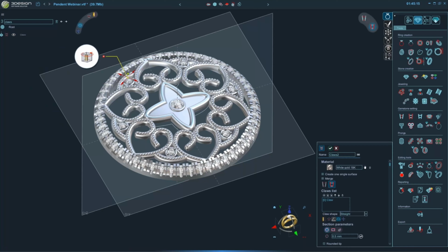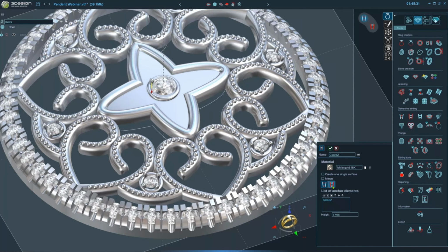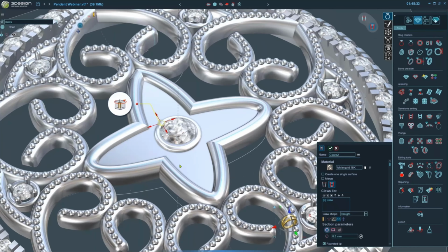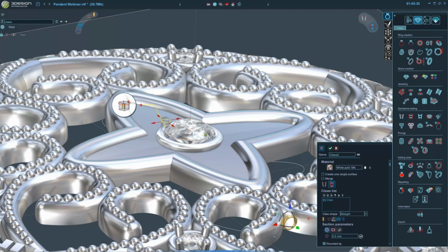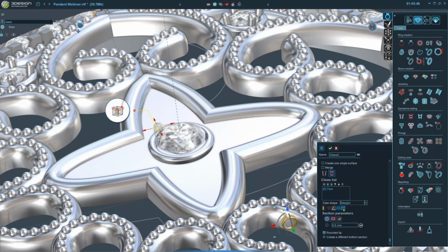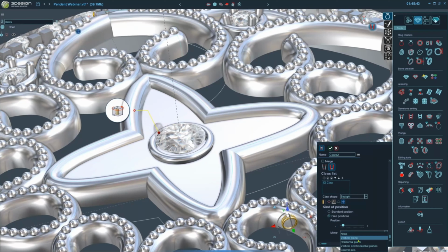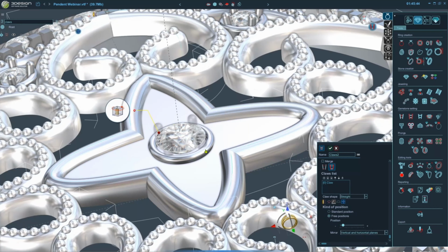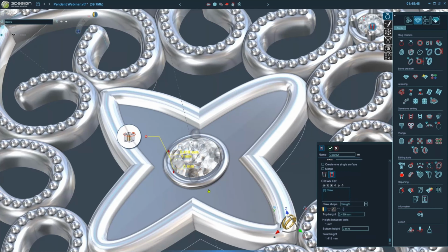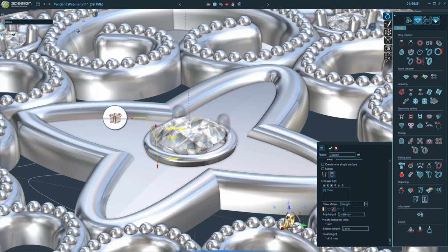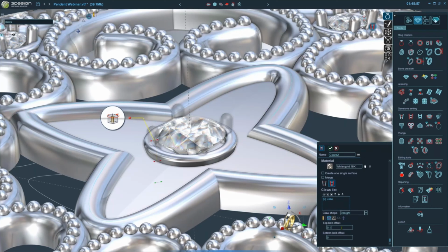So create a copy of the claws, and we're just going to do the same thing I did before and add this stone and get rid of the original jeweling. Sometimes because the stone is different, it turned off the mirroring here. There we go. This might be a case where that history is not helping much because I could have just done a new claw. I have to set everything manually anyway. The top height's there. The offset got reset.